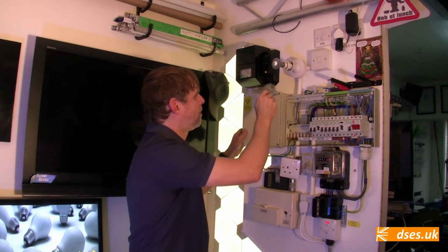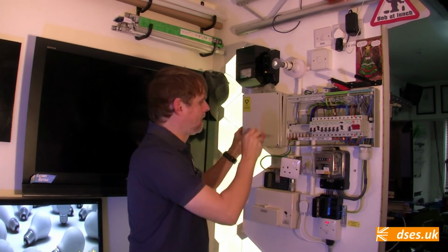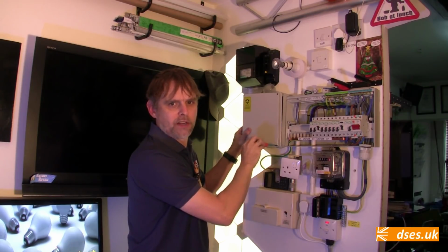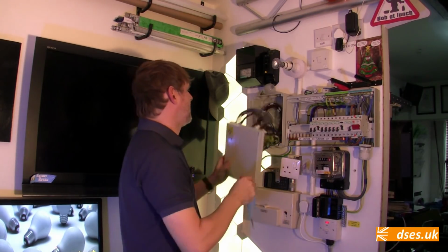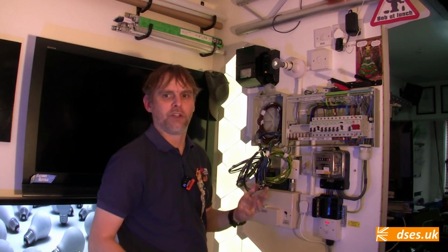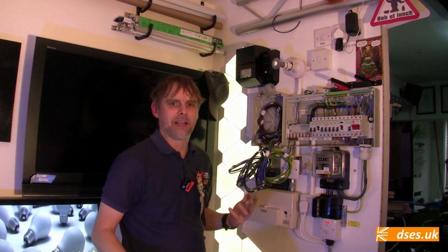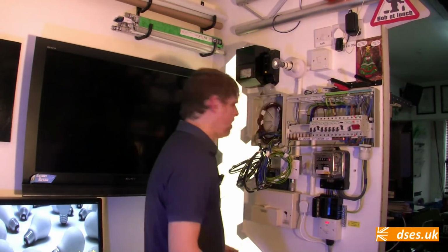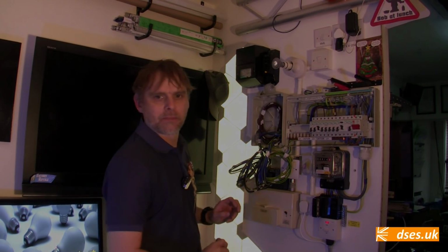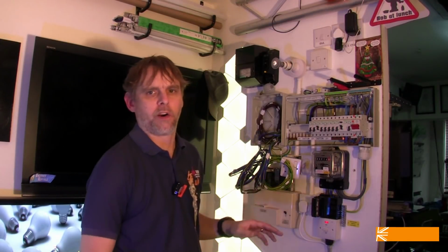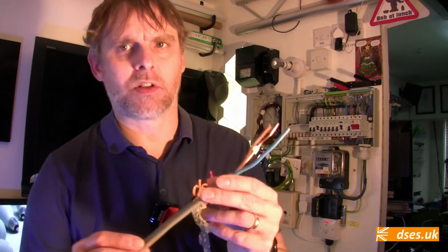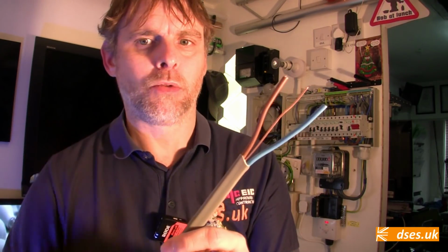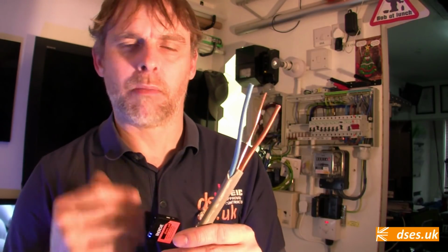Now, I've mentioned in at least one previous video that this grey box to the left contains several meters of wiring so that I can get some impedance numbers that aren't a big fat 0 whenever I perform R1+R2 or Zs testing on this thing. And if I take the lid off, then we can indeed see an excess of multicolour mess. Domestically speaking, normally your wiring would be self-contained for any given circuit, so the line, neutral and circuit protective conductor would be grouped together in a single sheath, such as in a flex, or for fixed building wiring in the UK, a twin and earth cable like this.